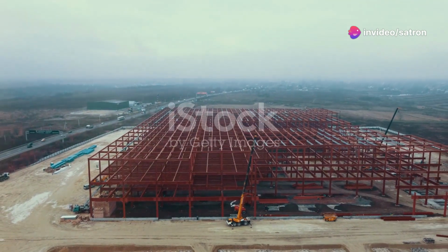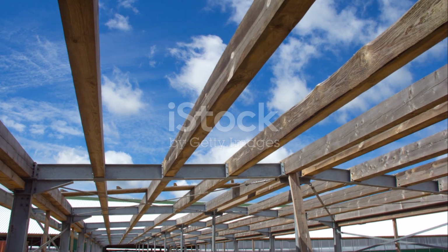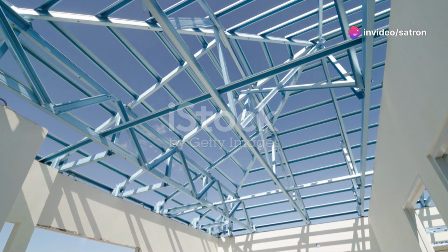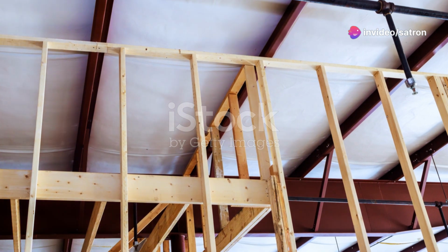One of the main advantages of open web joists is their lightweight nature. Compared to traditional timber or concrete framing, steel joists are significantly lighter, which reduces the overall dead load of the structure. This can lead to savings in foundation costs and allow for larger clear spans.